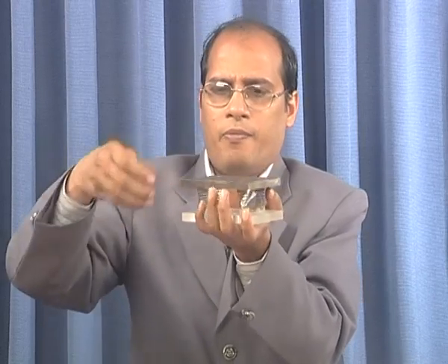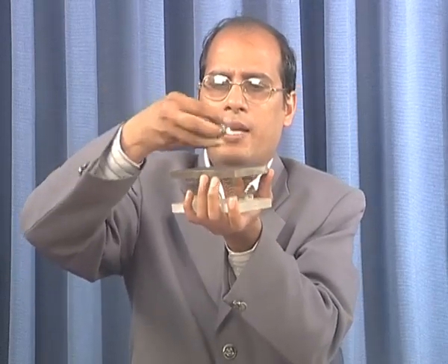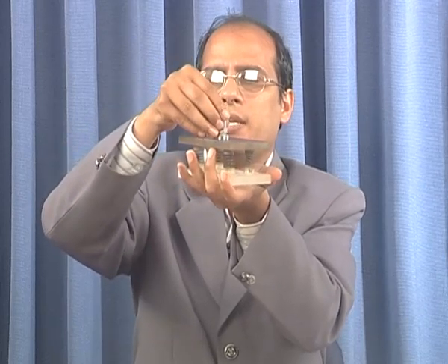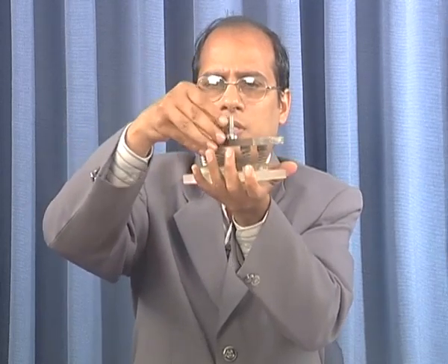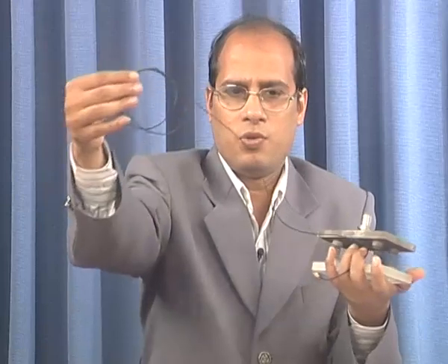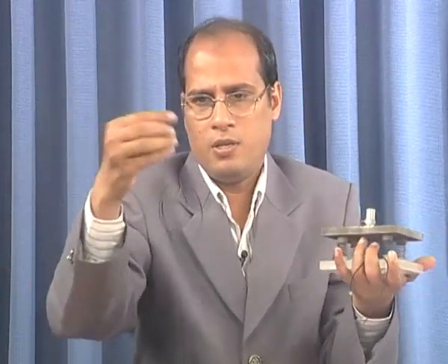Then that structure will contain a magnetic particle, so we are taking steel. In this case it is attached to the structure. So, when the structure is vibrating, you can take the response, the vibration of this, by using this wire. So, it can be taken to the data acquisition system,